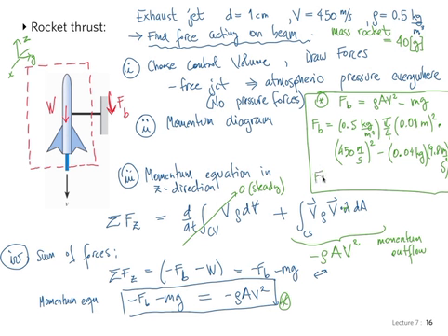So FB is known here, and I've already computed this, and we have 7.56 Newtons pointing upwards. That's the force on the beam. On the control volume, it points downwards. On the beam, it points upwards.